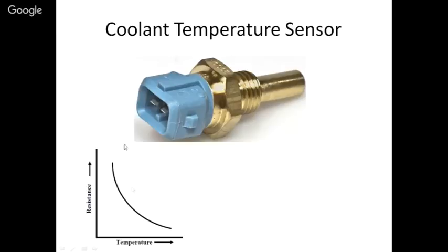So this plot is for an NTC type sensor, where with the temperature the resistance decreases. The advantage that these ceramic types have over the metallic type is that for R = R0(1 + αT), there will be a linear relation between resistance and temperature, and for a given temperature variation, the resistance variation is not that much, it is lesser.